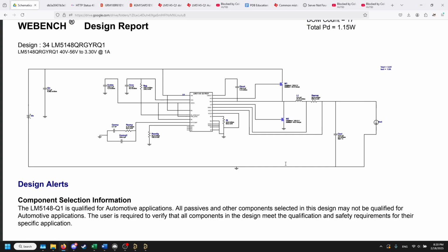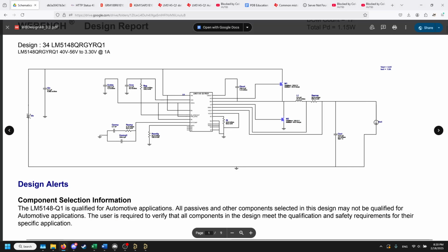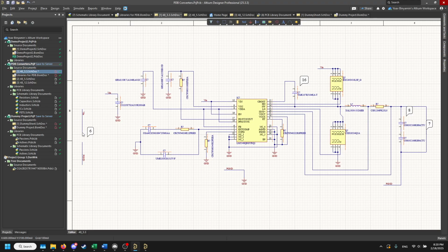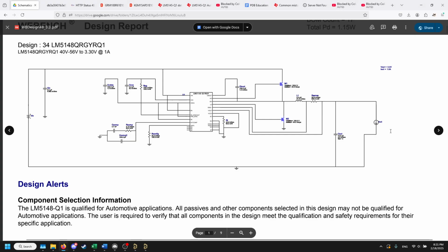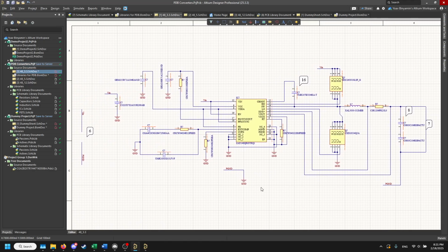On the left, we have a missing input voltage. This is just a placeholder for now. What I would do is place two vias or two pads, or a sort of connector pad, one pad to a VN and one pad to a power ground, which would make the connection. It's the same thing with the output current here. Currently we don't have that set up, but hopefully we should.